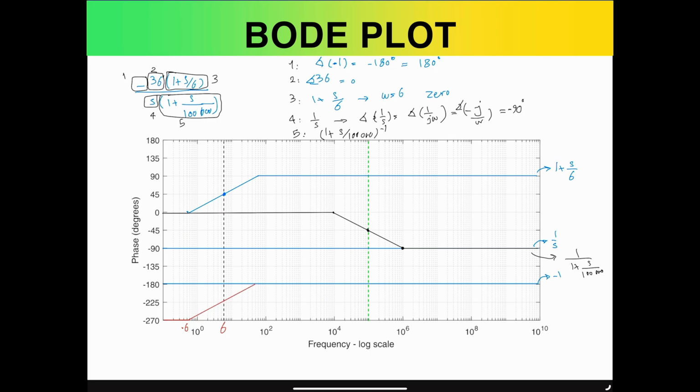So that's how pretty much this will work. After one decade, we increased 45 degrees, and another decade, we increased another 45 degrees to get to 90 degrees of total change. And now is the time to see what the new changes in the slope are. So this change is 0, this change is 0, this change is 0, this change is 0. It means that we are going to actually experience a 0 dB per decade, or zero angle per decade, for the rest of the phase diagram, up until this point where the angle changes. So until this point, we will have phase of 0.